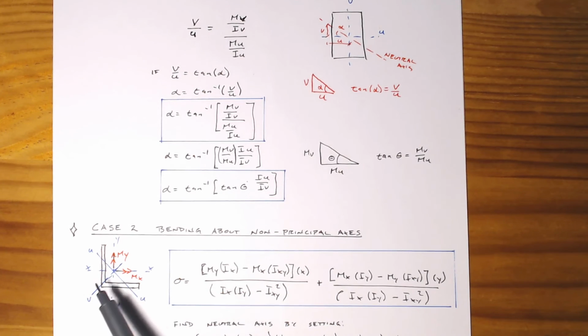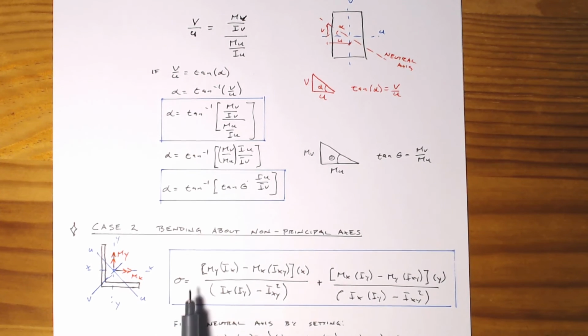So this is really useful when you have, maybe you're bending this, you have this set up as a beam. It's got a support along this bottom flange. It's going to have some bending Mx. It's not going to have any bending My, so the My terms cancel out. And then you're just working out your product of inertia and your moment of inertia about the y-axis. And so in that case, that's actually not that difficult to deal with. You just have to do a little bit of bookkeeping and keeping track of the equation. And so, again, that's how we find bending stress.